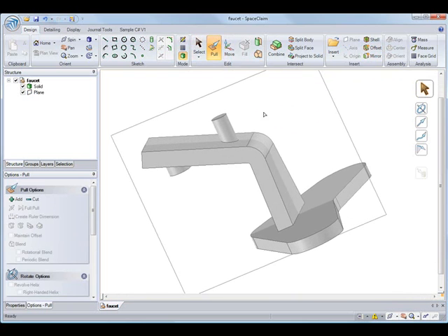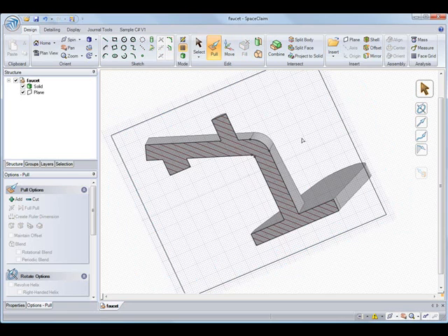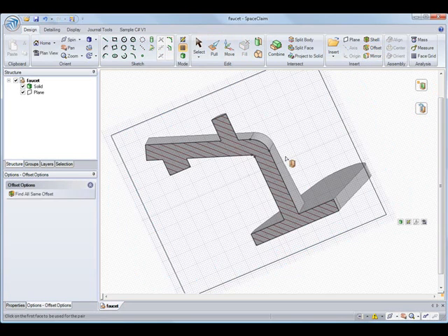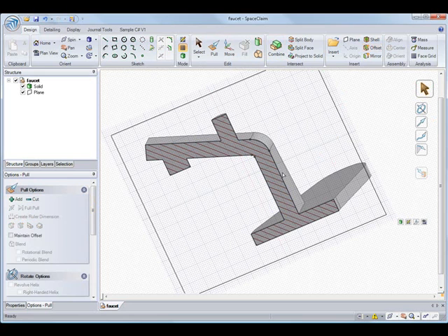And on our spout, you can see if I pull on it, it doesn't maintain any offset. So I want to put one in. And I can do that in 3D, or I can do it in a 2D cross-section. And all I have to do is click on offset, click one face, and then click a parallel face. And now anywhere that distance is located, we can now see an offset baseline appear. And I can also toggle it from one side to the next.